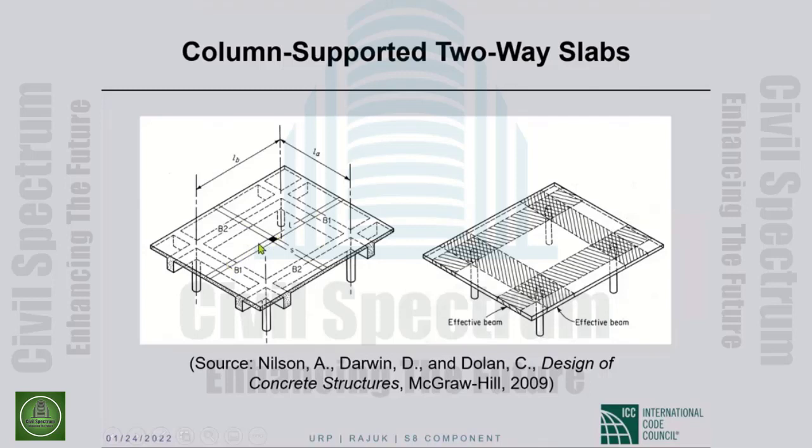Now the 40% of the slab loads that are transferred by bending in the long direction, those loads are transferred to beams B1 which span in the short direction. Okay, so 60% of the load on the slab is transferred by bending of the slab strips spanning in the short direction, and the remaining 40% of the load on the slab is transferred by the beams bending in the short direction to the supporting beams.